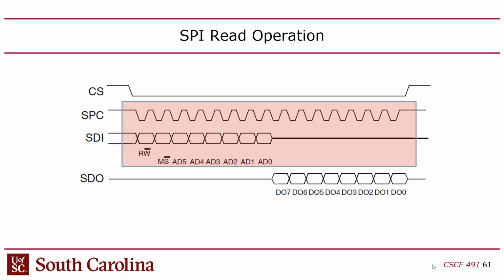And then once this gets through, you're either going to receive data back from the other side if it's a read, or you're going to just continue sending bits if it's a write, in which case this line is going to be totally dead the whole time, right? Now you might say, wait a second, why doesn't the slave send back an acknowledgement or something? I don't know. They never do that. They should. They could use this time for something, but they generally don't.